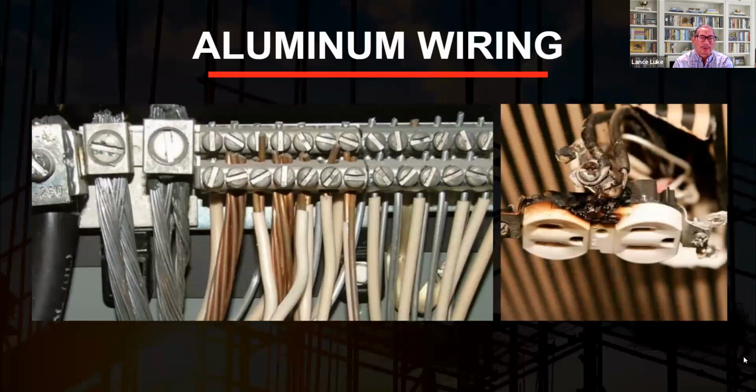Okay, what happens is the aluminum wiring corrodes easier than copper, and it also heats up faster. And there have been cases of fires that were started because of aluminum wiring. What happens too is that the screw that holds the wire into the device may get corroded or may get loose, and then when it gets loose and there's no contact, the electricity has to go somewhere, and that's what arcing is all about. Arcing is the electricity jumping at the end of the wire to something else because it doesn't have a termination connection.